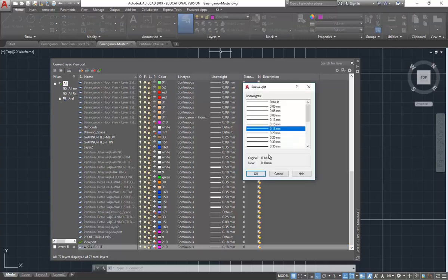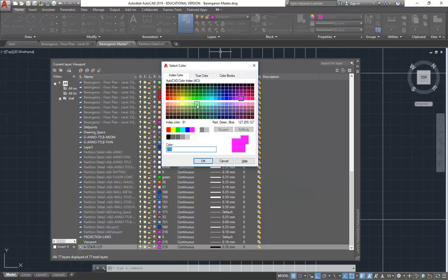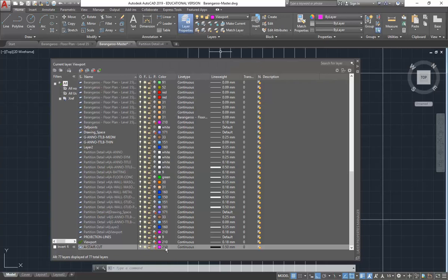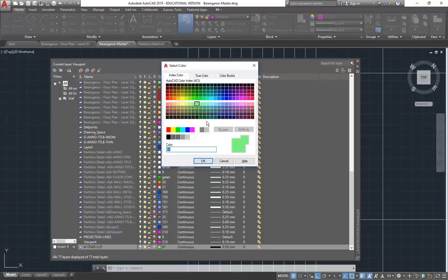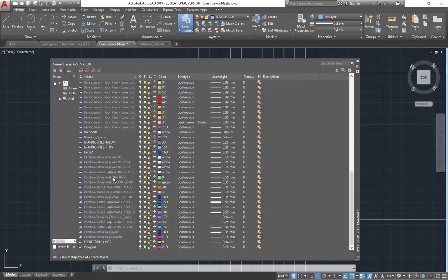I'm not going to be checking your layer names. And then I'm going to make this fairly heavy because it's going to be almost like a detail, so I can make it 0.5. And the colour I'll make just something that'll stand out, green, that'll do. It's probably metal, so it probably should be really a bluish sort of colour. But again, don't get hung up on the colours needing to follow a standard or anything like that. So that should do it.